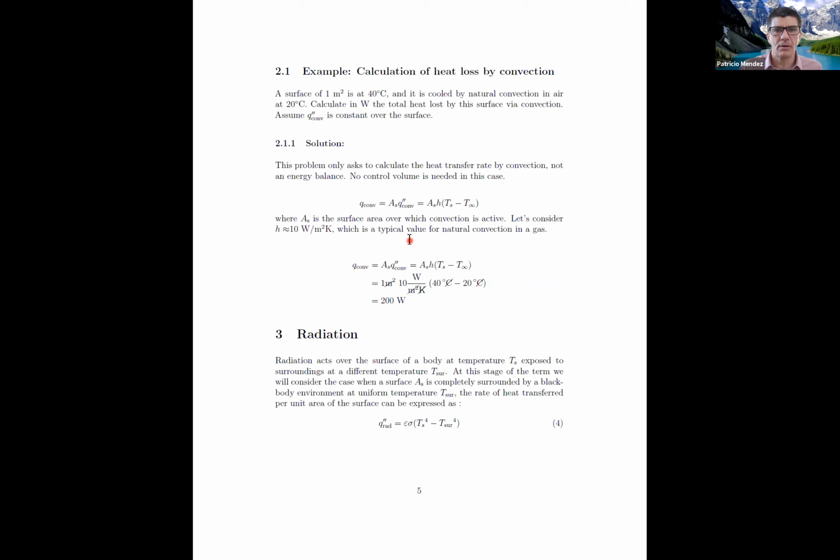Let me tell you about radiation now. Radiation is interesting. Radiation has a more complex formula, but it has a similar spirit. The origins of this get into quantum physics, and we don't need to know quantum physics because we're engineers, but we know how to reduce it to a practical formula. It says that the heat flux exchanged by radiation has this formula in which we have epsilon sigma (Ts^4 - Tsurr^4).